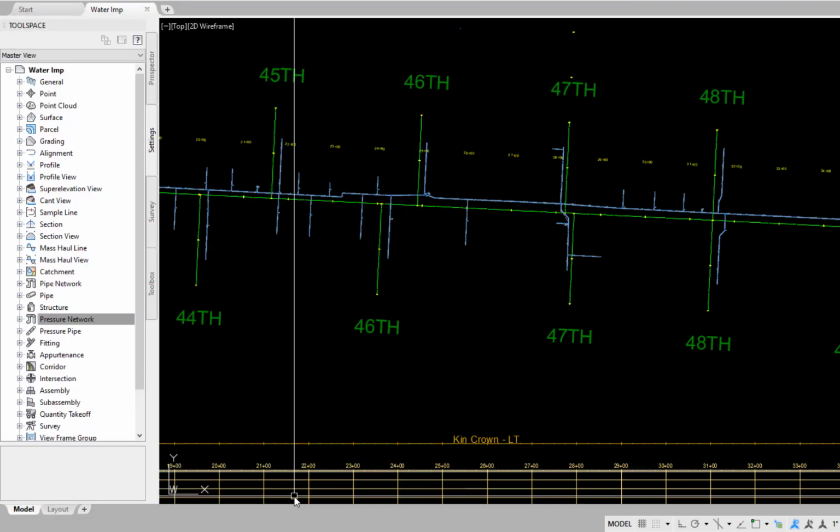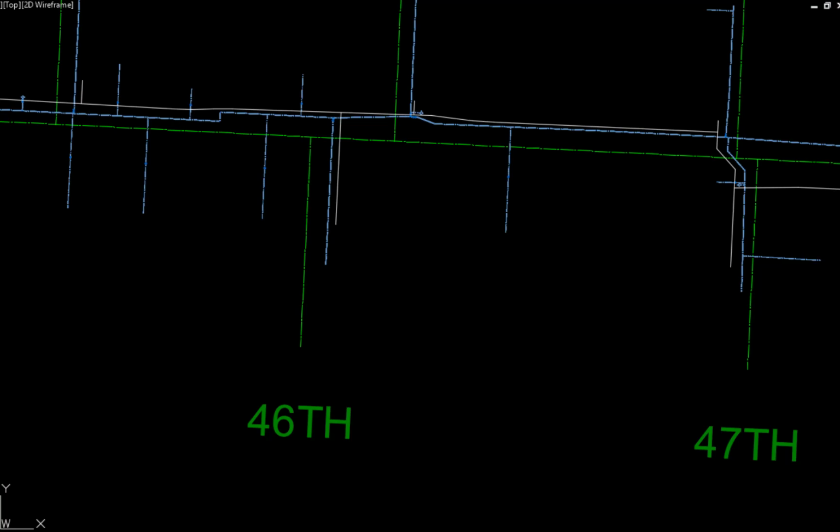OK. Lines are generally drawn on layer 1 for the preliminary layout of the construct water main system. For this video, the layout lines have been drawn and are shown. Angles in the alignment are drawn at small deflections less than 5 degrees that will allow the creation of the water pipe deflections without bend using the pipes only creation method. At locations where greater deflections are required, the lines are drawn at standard bend angles for using the pipes and bends creation method.